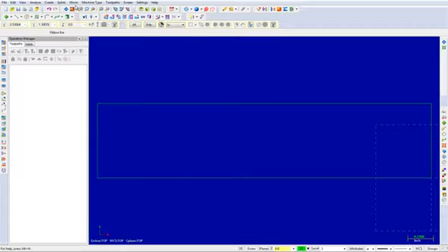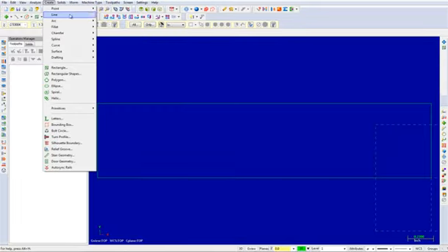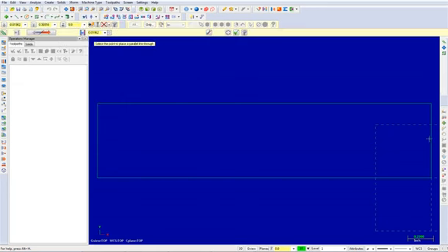Next, we will create parallel lines. Select the Create Line Parallel command and pick Entity A as shown. Now pick a point to the left of the selected line and enter in a distance of 0.75. Press Enter and select the Apply button to stay within the command. Repeat this process again, selecting Entity A as a basis line and inputting distances of 1.5 and 1.65.